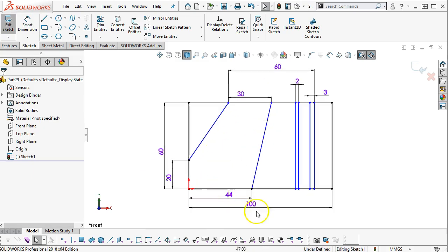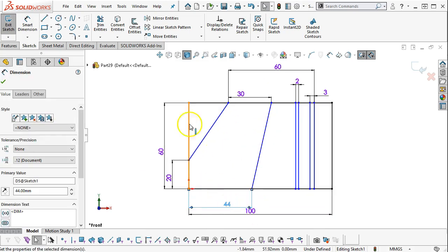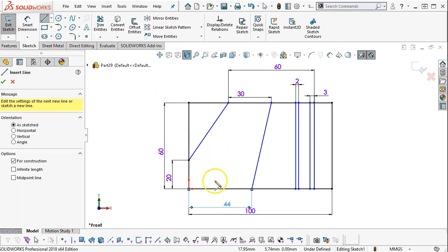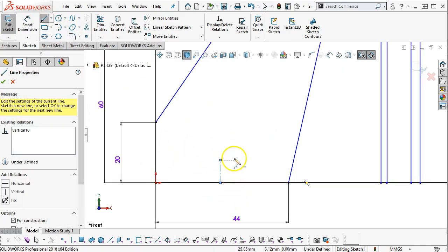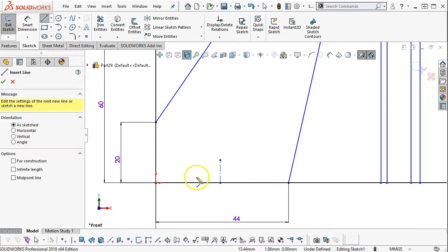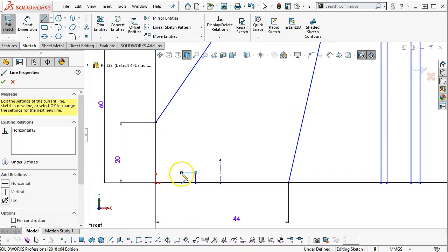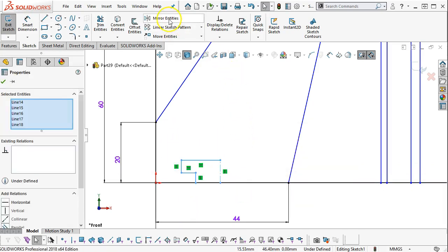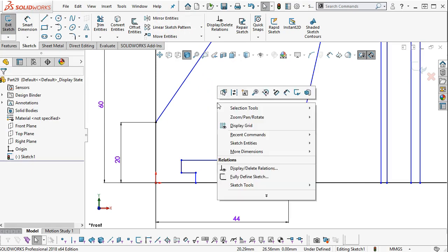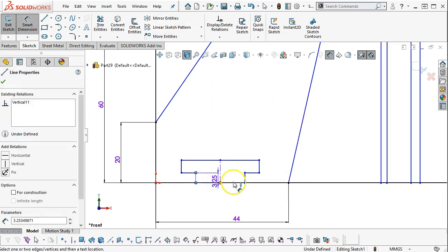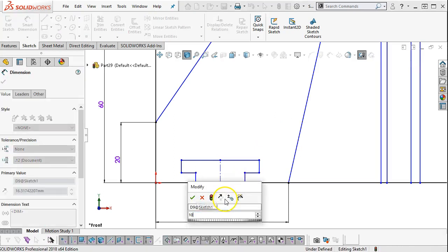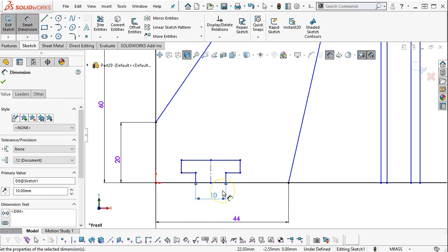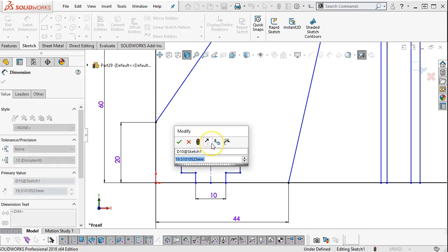All right, so the path that I took this time is not getting me to fully define very fast. So let's go up, over, and back for the T slot. And then all of that can be mirrored. Well, maybe not all of it. We'll go with the left to right. 10 millimeters on the opening. Looks like 5 millimeters. No, give it 20 millimeters on the overall.